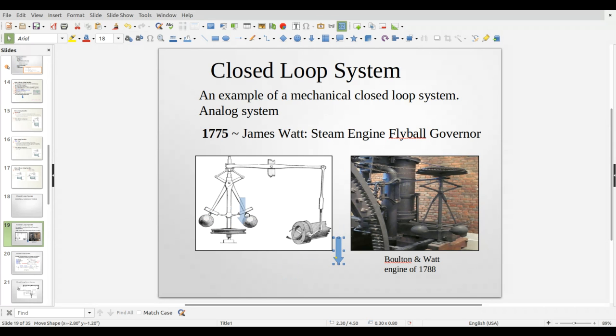And as you know, as you spin around a heavy weight, the faster you spin it, these things move further and further out, right? The inertia, as you're spinning it around, makes these fly out. But the scissor action brings this lever down. And if this lever goes down, then this lever over here goes up, which closes the valve, which slows down the system. All right. And when the system starts slowing down too much, let's say you put a load on it and it starts bogging down, so you need more,